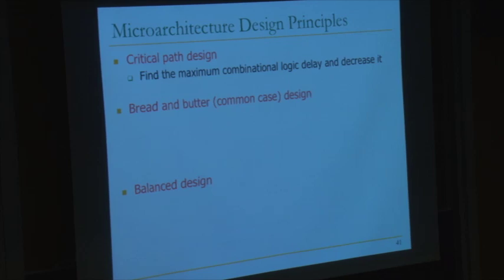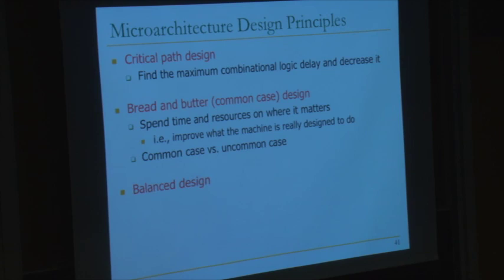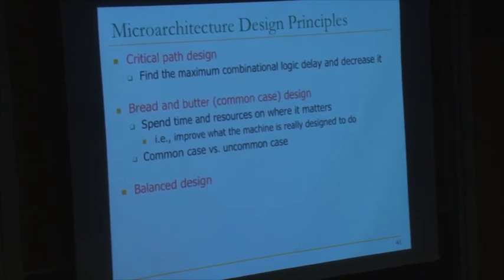Right? Second thing, and this is actually true, you want to do this in a single cycle microarchitecture too. Actually, you want to do this really badly in a single cycle microarchitecture because you have only a single cycle to deal with. The second thing that is violated by the single cycle microarchitecture is common case design, or this is called bread and butter design as well. Basically, spend time and resources where it really matters.